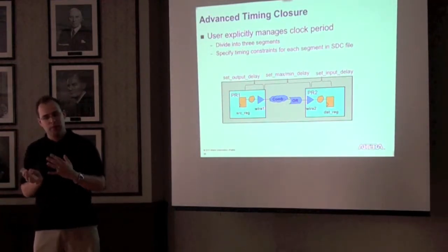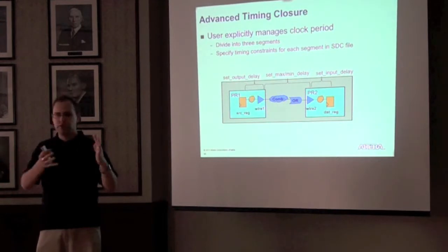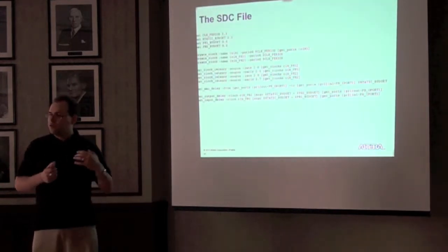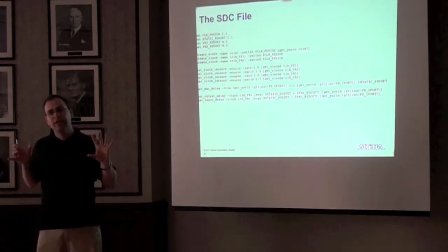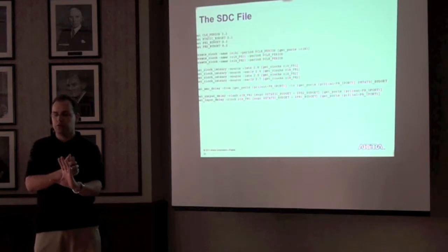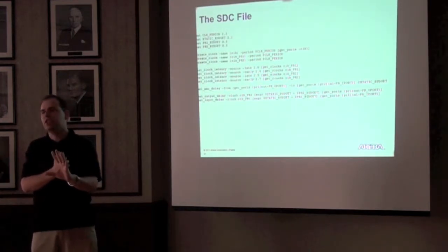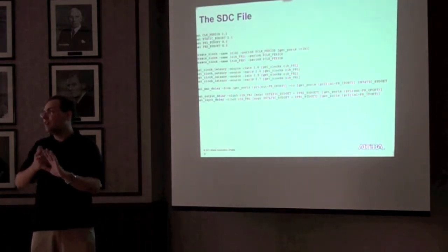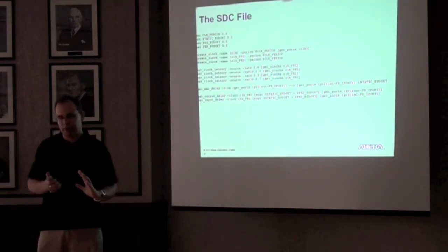Again, no given compile will see the end-to-end path, so you need to budget it to ensure that the end-to-end one is met. Using an aggregate revision, you can actually bring in the full combination and guarantee that it will work, but Quartus will say that if you violated your budget, you have failed timing. But that actually doesn't represent a complete failure if every combination of the aggregates will pass.